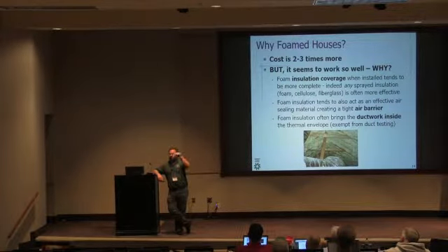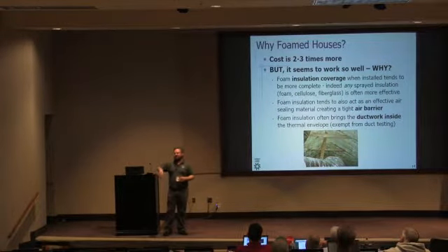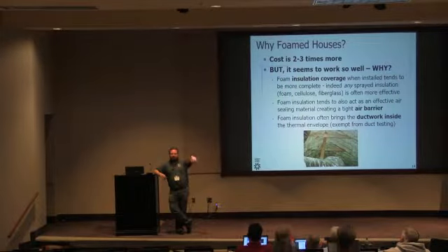And then I'm not going to make penetrations in my drywall ceiling. I'm going to caulk my drywall where it butt joints in the ceiling, and I'm going to caulk it where it hits top plates, and I'm going to avoid penetrating my drywalled ceiling. If I were building the house, that's how I would do it.